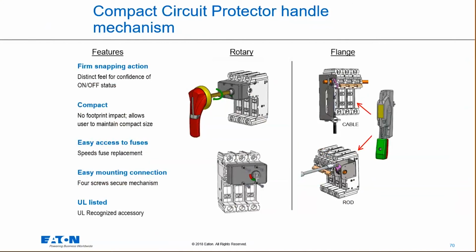And even if you decide you don't want to use a disconnect version, our fuse holders themselves, guys, if you look at a 100 amp Class J finger safe fuse holder, our 100 amp Class CF, which is a cube fuse, is probably half the size. And dollar for dollar, it's actually less expensive to put a system together with a cube fuse because it is all finger touch safe. And it is a lot smaller in footprint as well. So I encourage you strongly to look at it if you haven't already.